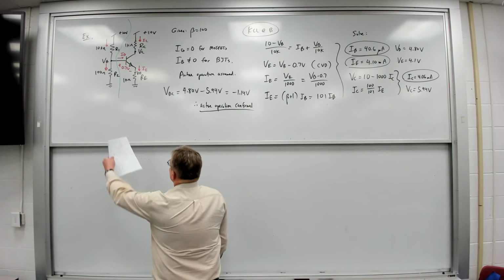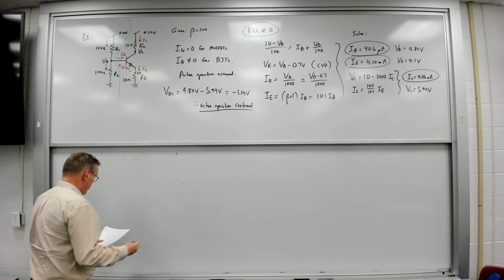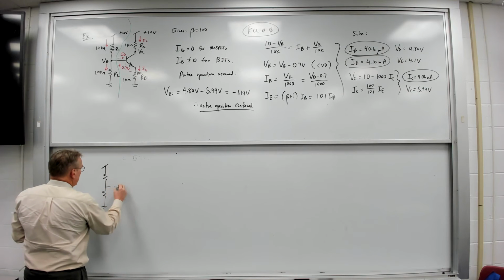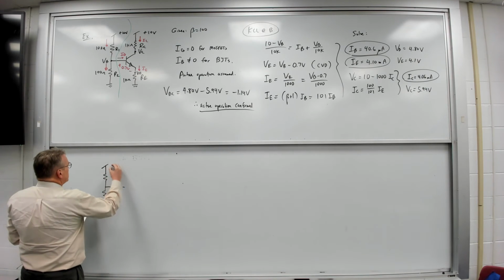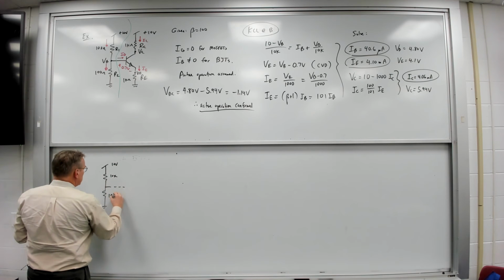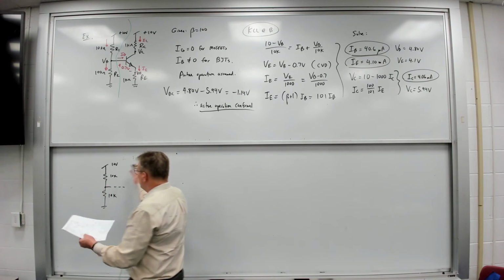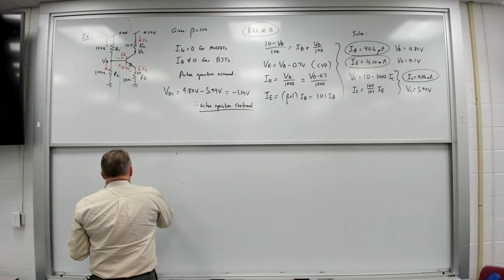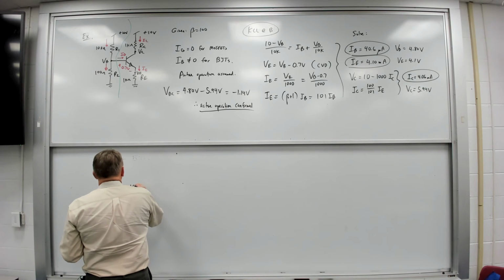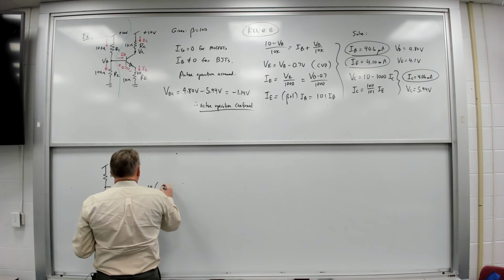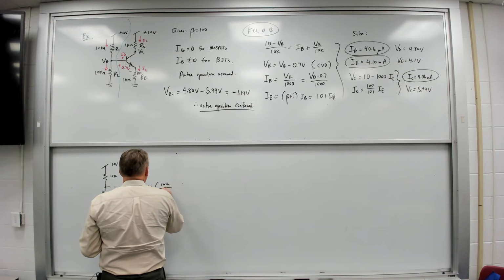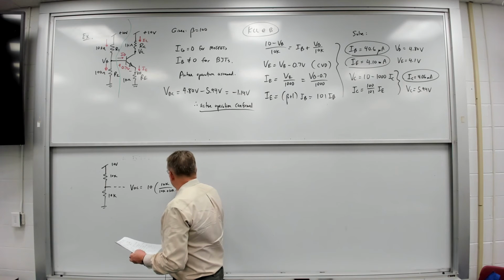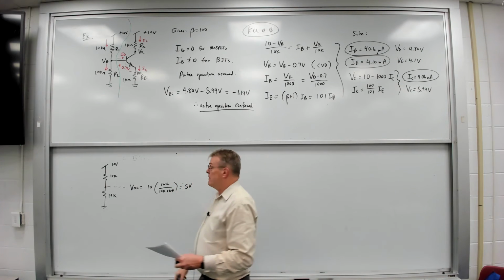So the Thevenin equivalent of that voltage divider: I've disconnected the load. I've got 10K, 10 volts, 10K. First of all, having removed the load, what's the open circuit voltage? In this case, it's very easy. The open circuit voltage VOC is equal to 10 multiplied times 10K over 10K plus 10K, and that'll be equal to 5 volts. And so that's my Thevenin equivalent voltage.